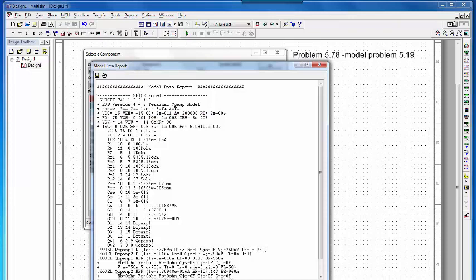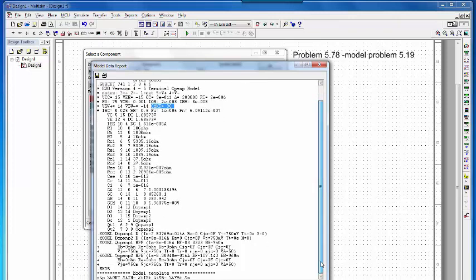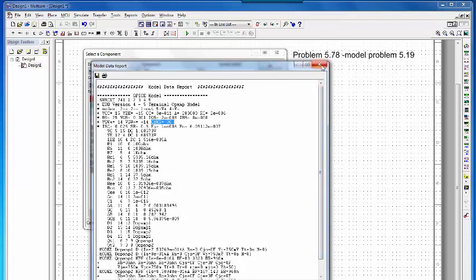And there's a common mode rejection ratio, which we haven't really talked about yet, but that's how good it rejects the common noise to both terminals. So the whole internal model for the op-amp is hidden here underneath, and it is a SPICE model. All these modeling programs have SPICE underneath. It's kind of interesting. Okay, so there's your model.